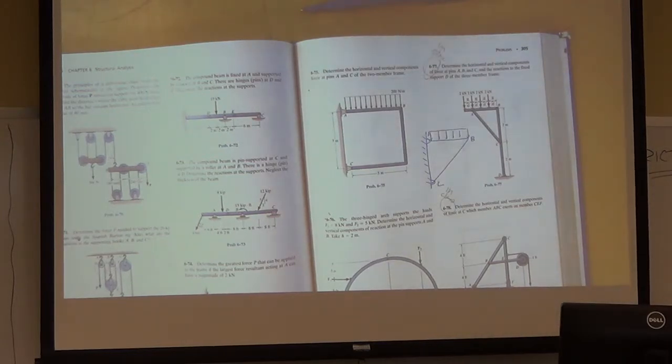Going back to one of the examples that we worked through in class, if we were to first draw the free body diagram of the whole structure, and then, just for the sake of argument, draw the free body diagram of member ABC without the connections, would you have an AY prime and an AX prime sort of situation?